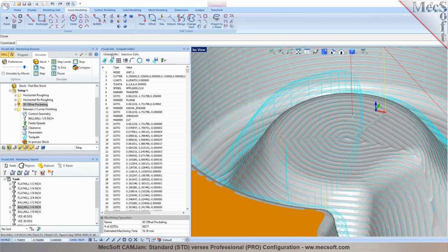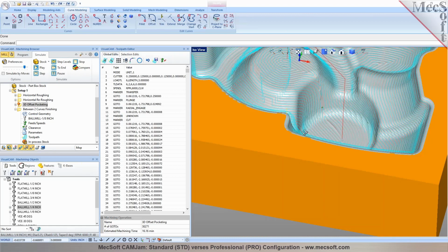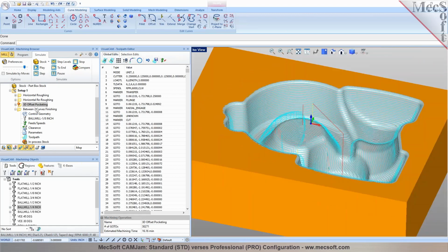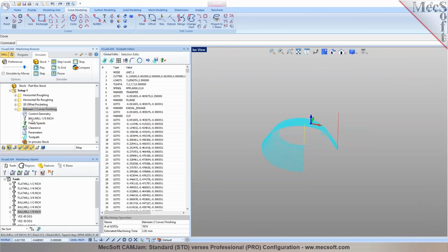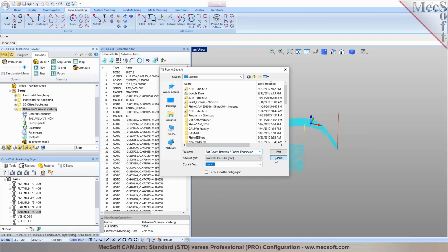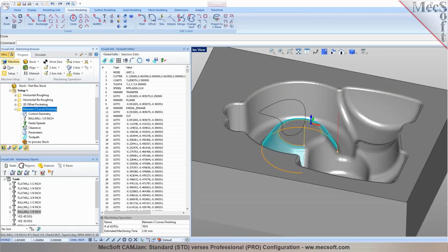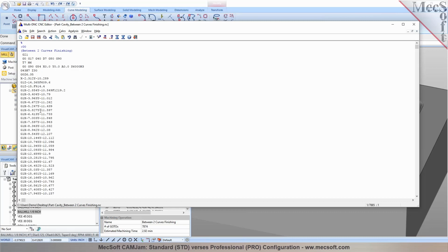or you can even convert those to curves. Can you go right into the G code and manually edit any positions or anything like that, as far as just typing them in? Okay, so when you post-process a toolpath, let's do a post. And we typically post it out to a notepad, or you can use any third-party editor. I'm going to do a post, and I actually have a third-party editor in here, and this is where the posted code pulls up right there. So you can manually modify this code in here. Yeah. You can edit this out.